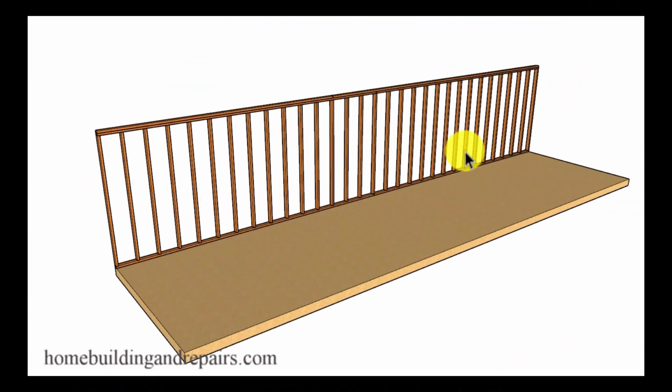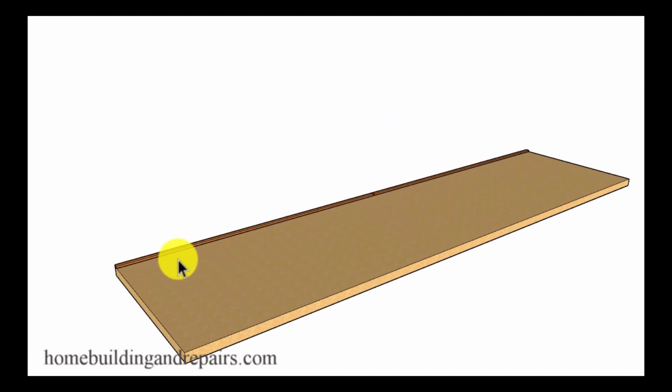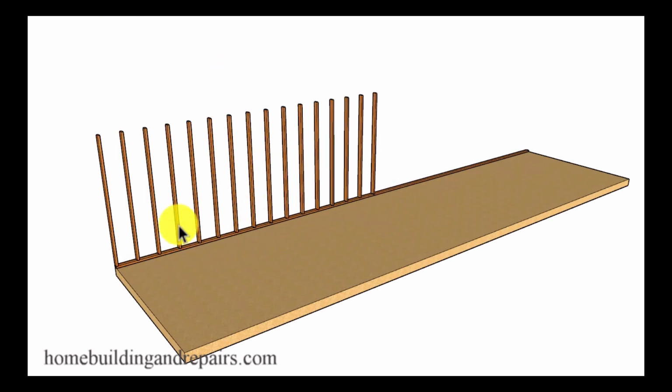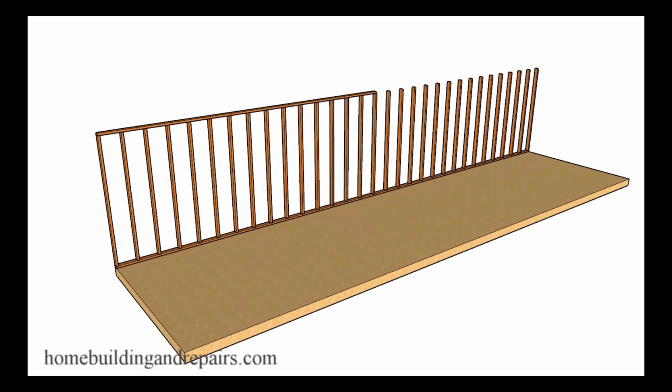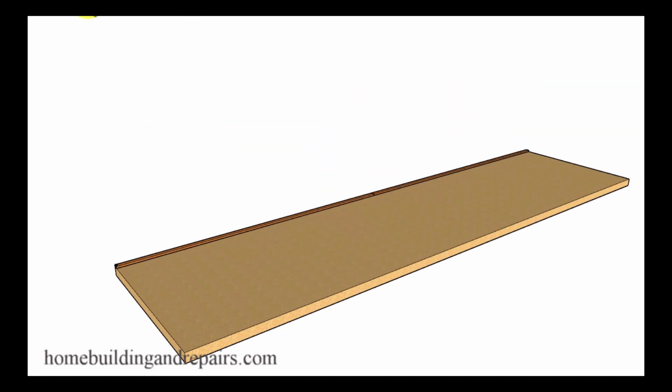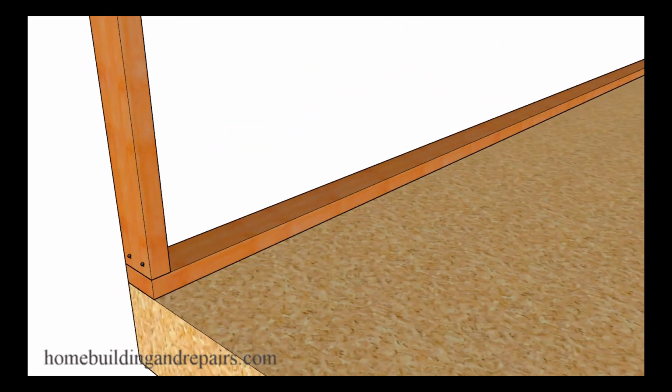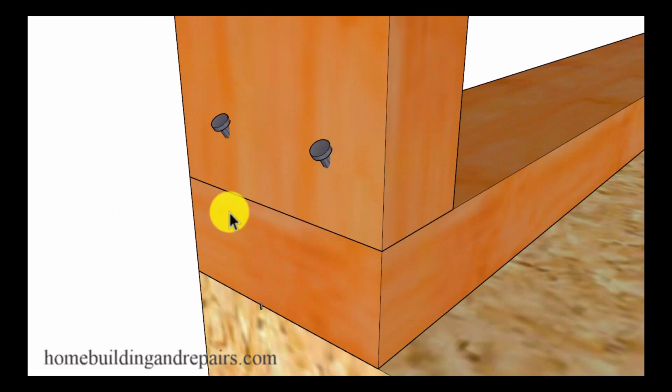So basically, if you have a long wall, you're simply going to start with your framing plate. Attach it securely to the foundation, because a framing plate is going to help support the vertical wall framing studs. However, this won't always be the case. You might need to install additional braces or build one section of the wall at a time.